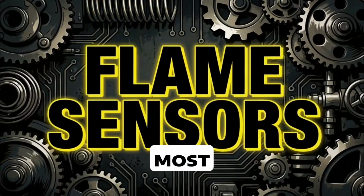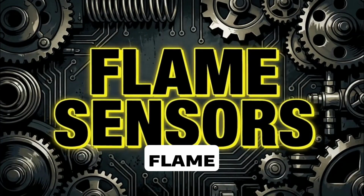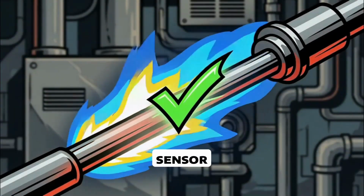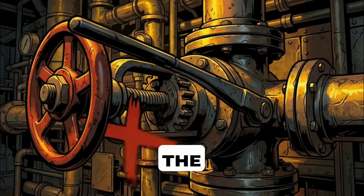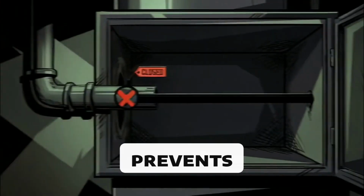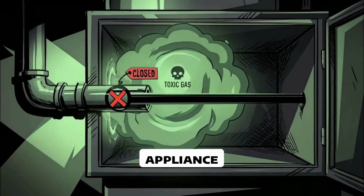Now, one of the most tested topics: flame sensors. A flame sensor proves flame exists. If no flame is detected, the gas valve shuts off. That prevents raw gas from filling the appliance.